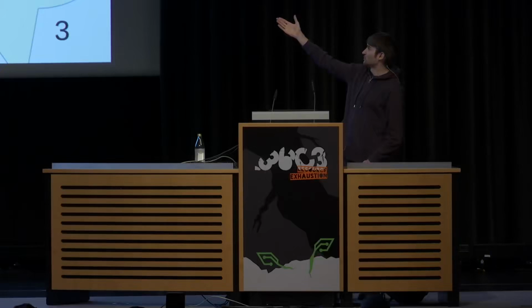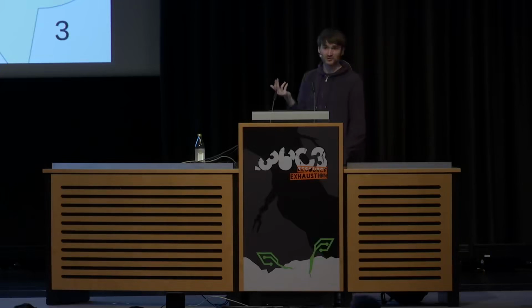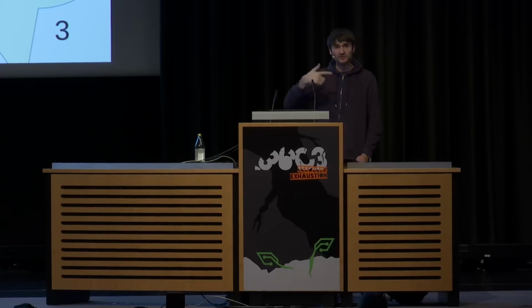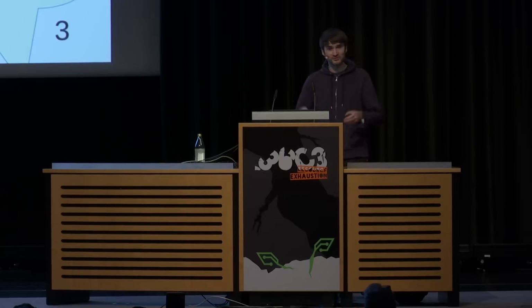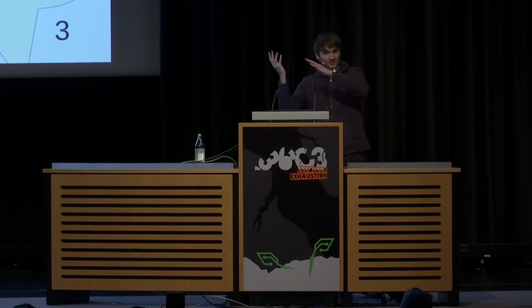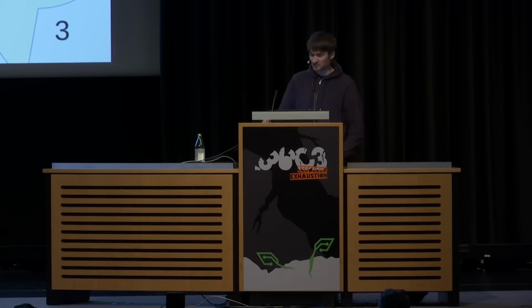So I wrote here that we are using UDP packets, and this seems to be a smart choice because it's unidirectional, so you just send data from the drone to the ground station and avoid all the hiccups of, let's say, stream-oriented protocols like TCP. So data could queue up, you need to send acknowledgements up to the drone, which is of course not really something you would want to do. So UDP seems to be a good choice.